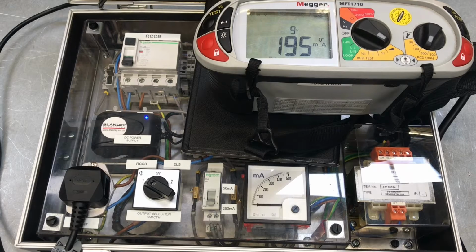And this is why you guys are being taught about the hazards of AC type RCDs. When they came out, they were fine. They were fit for purpose. We had resistive loads everywhere in our houses. Now we have low energy, we have electronic loads. So those protection characteristics can cause effectively unseen hazards that we now need to be considering.